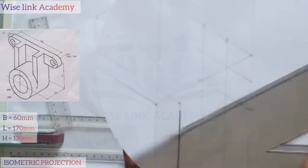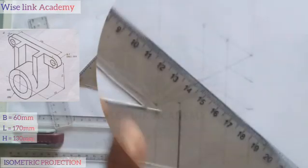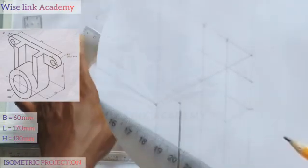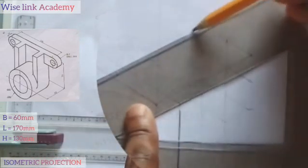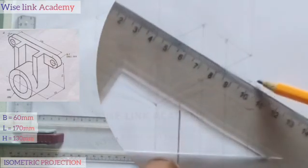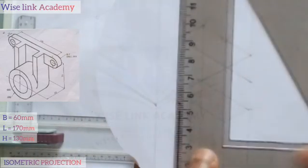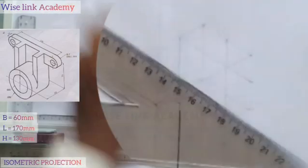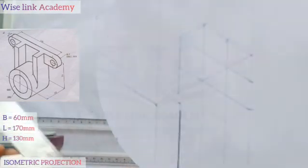Take this edge point here down this way, and extend this point here down with a faint line. So I will take, at this point here, take it down this way. As you can see, next up, I will extend this line down. So take this point where they meet down to touch that line you have drawn initially, and extend this line this way. So I have produced the box, as you can see.